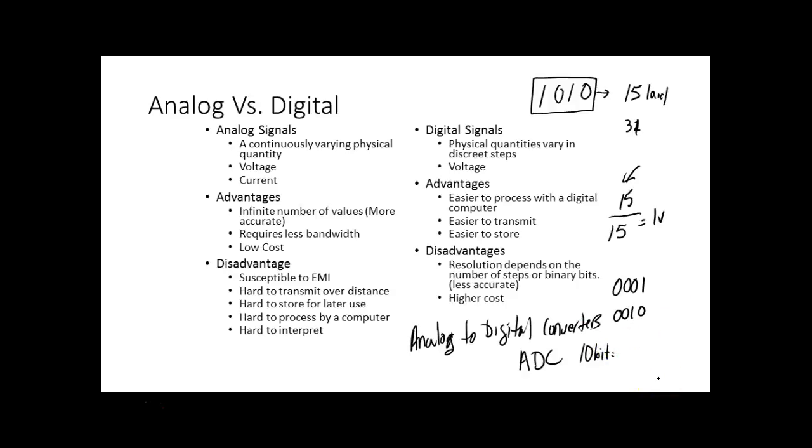Now I can calculate the number of combinations by taking the base I'm dealing with, which is base 2, and raising that base to the power of the number of bits that we're using. So if it's a 10-bit analog converter, this gives me the number of numerical combinations, which would be 1024. So I can take my input now and split it into 1023 different numbers. That makes sense.